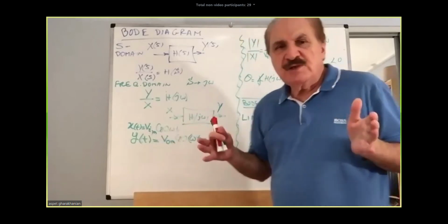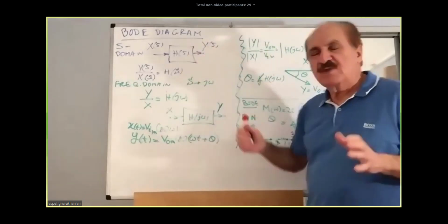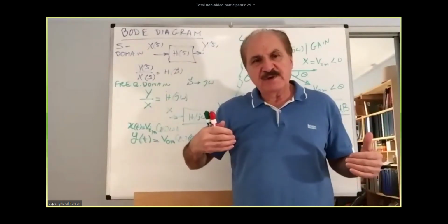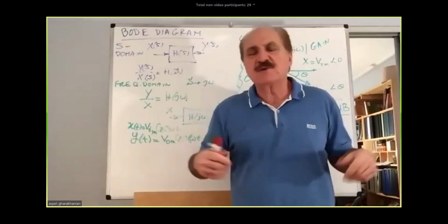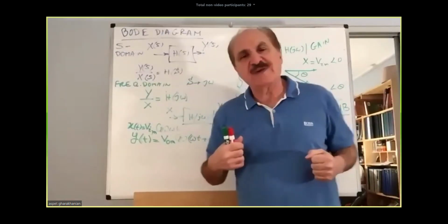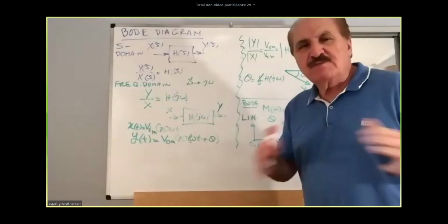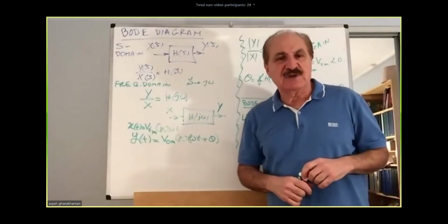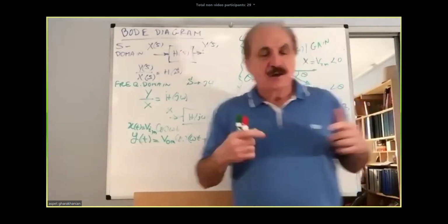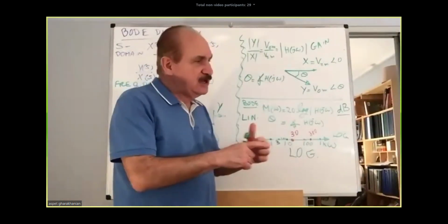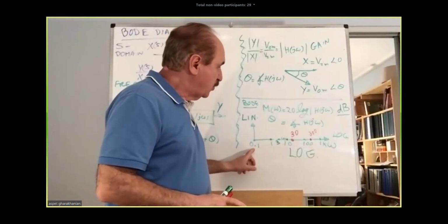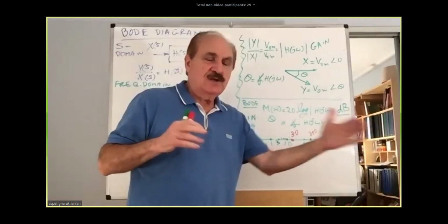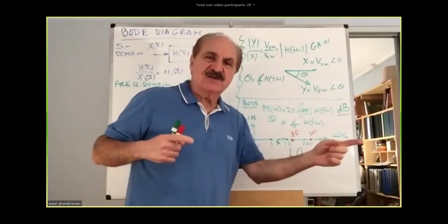Now, when we're doing the Bode plots, definitely go for logarithmic scale. The vertical will be linear, and then the horizontal will be logarithmic. It would be impossible to use a linear and linear scale successfully for frequency, because you can never in a linear scale show 0.1 radian and 1000 radian. You can never catch it within the span of the axis.